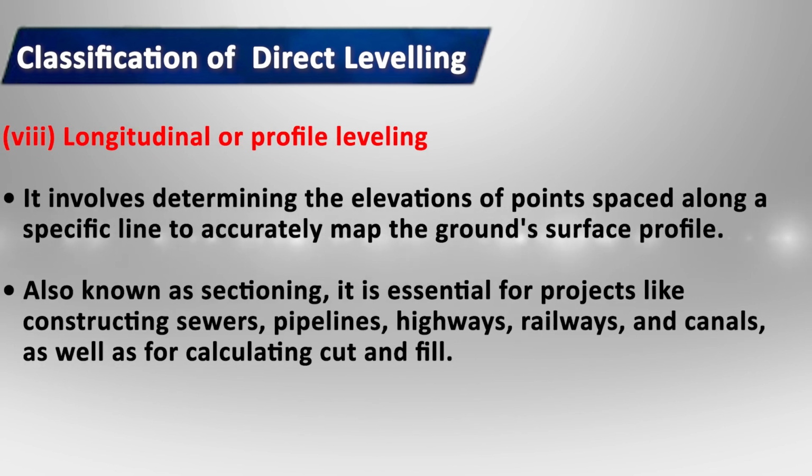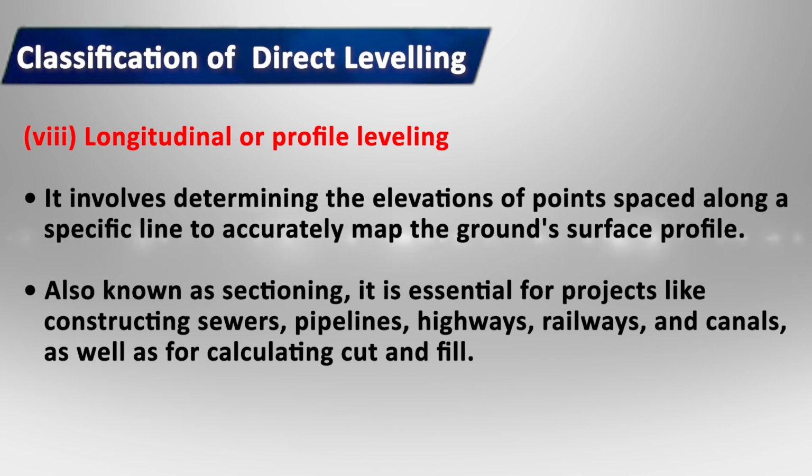Next type is longitudinal or profile leveling. It involves determining the elevation of points spaced along a specific line to accurately map the ground's surface profile, also known as sectioning. It is essential for projects like constructing sewers, pipelines, highways, railways, canals, etc., as well as for calculating cut and fill. The process relies on differential leveling, requiring multiple change points and intermediate sites at key locations such as slope changes or breaks in the ground.